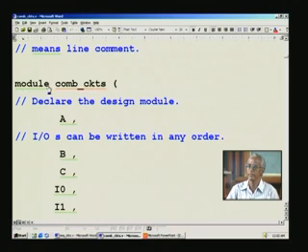And once again we see there is a module here, and the code might be a long thing. So, you normally tend to forget an endmodule towards the end. If you forget, the compiler will tell you, but initially for beginners it may be difficult. So, a good practice would be to put module and straight away endmodule and keep on keying in things in between so that you will not forget. And once again we have braces here. There will be a start here and an end brace toward the end, and we will have to declare all the IOs here.